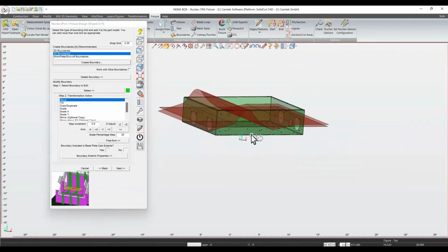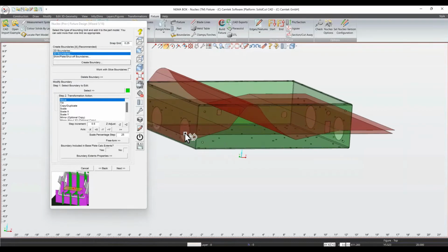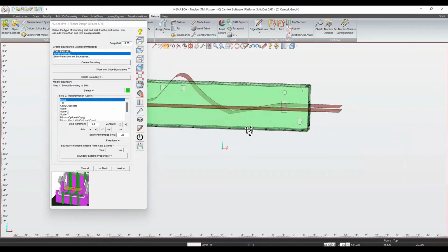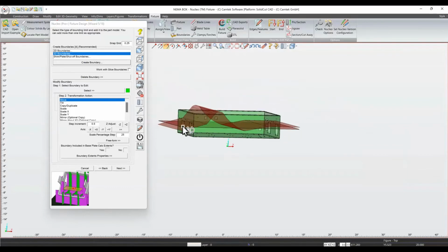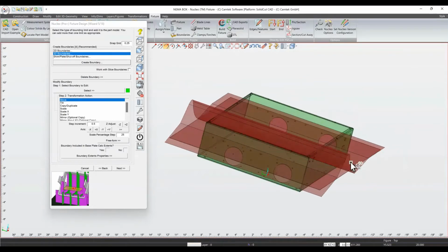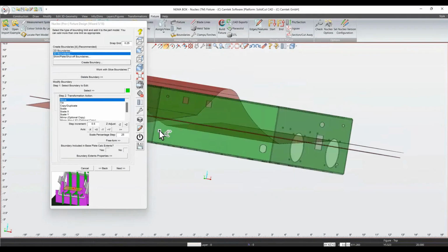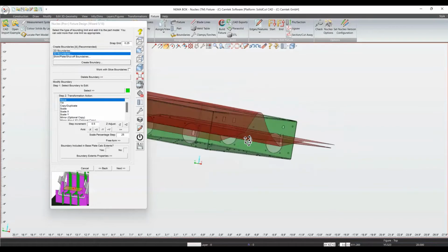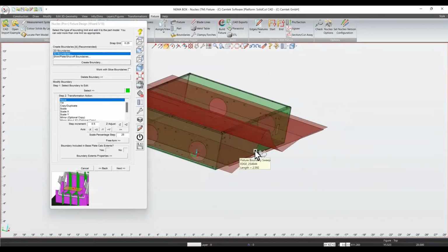And now what you can see is I have the two different boundaries. When you have overlapping boundaries, it's sort of like first come, first served. The first boundary that it intersects will be the boundary that it uses. So looking at it from this perspective over here, when we're outside the box, we'll be hitting this boundary out here, the flat boundary, then it'll dip back down, come back up, and then go straight back out. So it's a little preview of how you can imagine what your fixture is going to look like, if you need to make any changes.